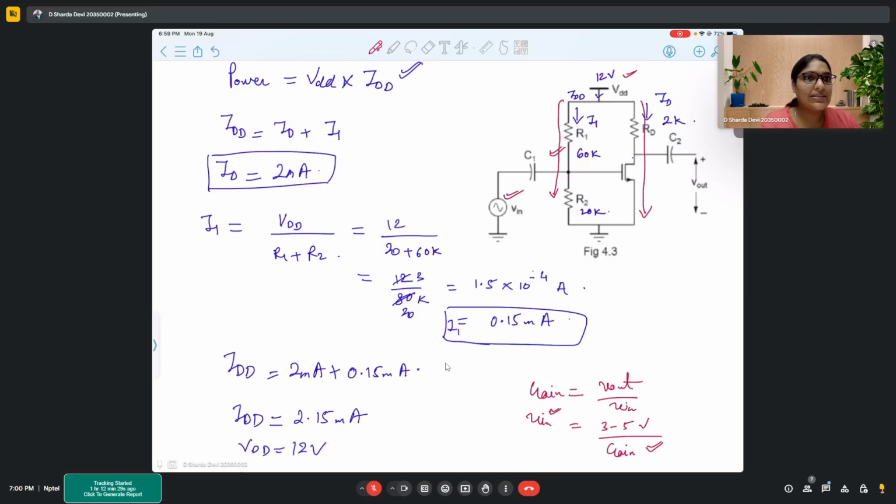So the range is different. For very large gain amplifiers, since output range is fixed, your inputs will be very small values, like let's say nanovolts or even picovolts. And if it is a single stage amplifier, it will be in a few microvolts. So that's how things change.